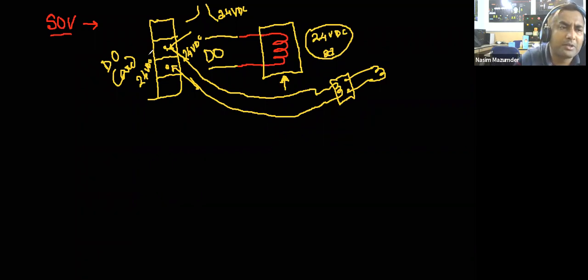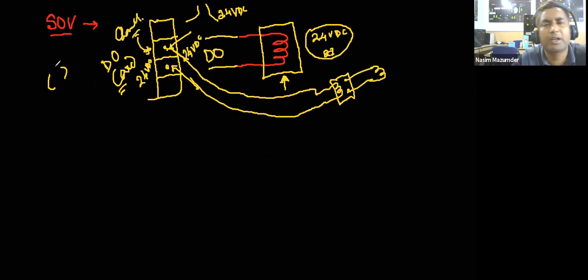And since it is a simple digital output channel you are using, in your logic you have to identify the address of this channel and configure it accordingly.